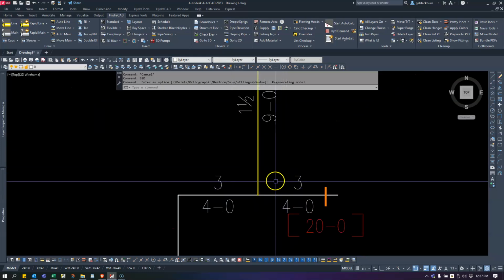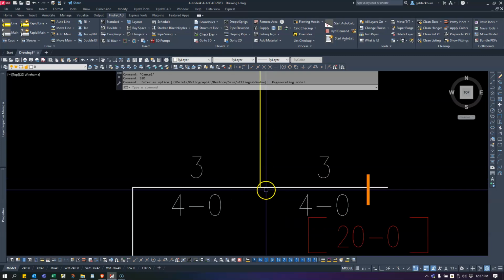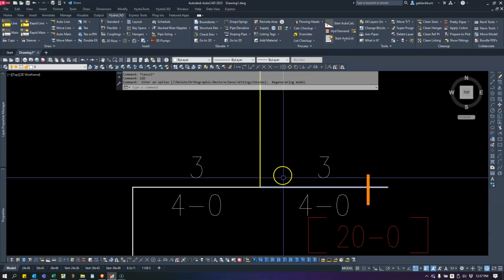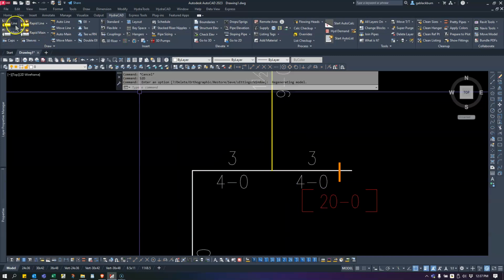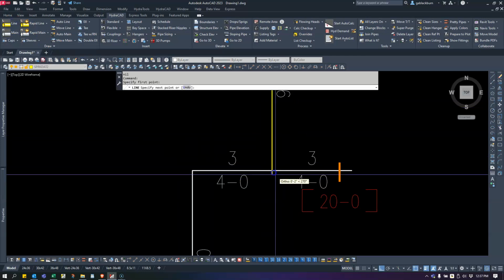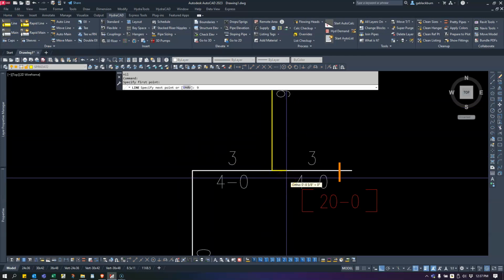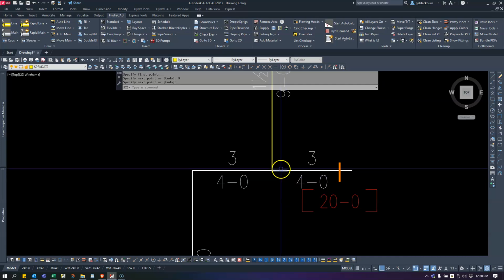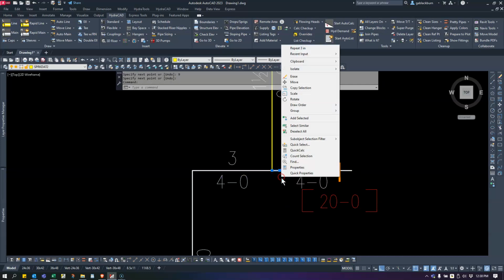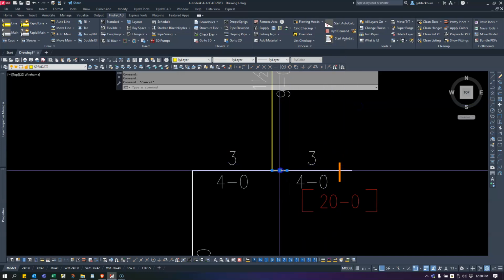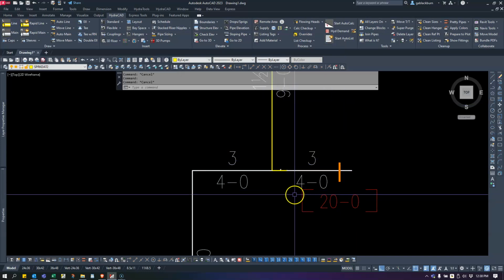And here's how I need to get this to have the pipe come up and draw over. So I'm going to first draw another branch line that comes over, let's call it 9 inches. So it's going to be back to back 9 inches. And let's just move this to the front. So draw order, bring to the front. So now we can tell that this yellow pipe is on top of the white pipe here.